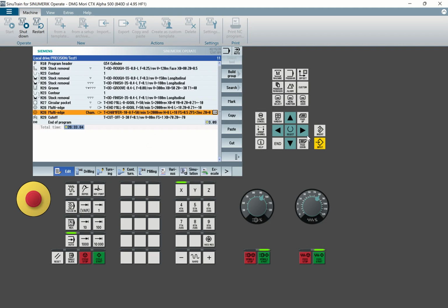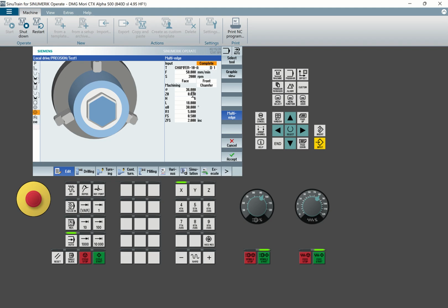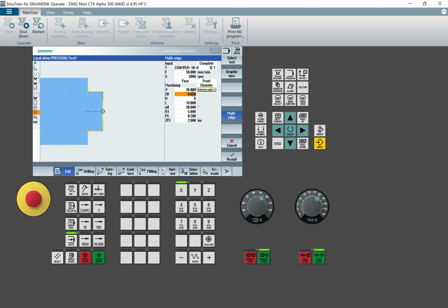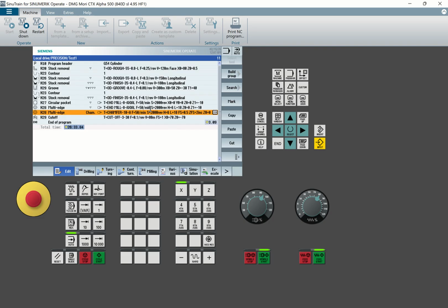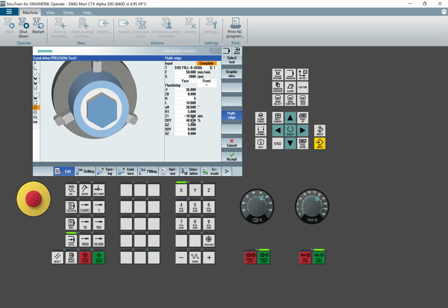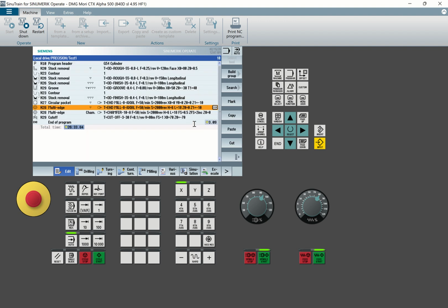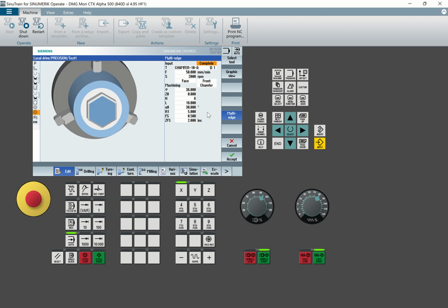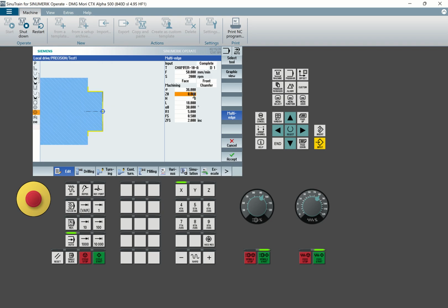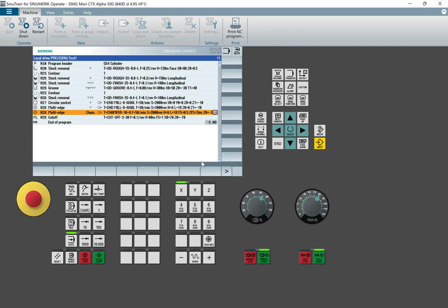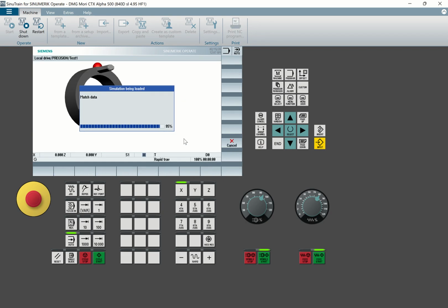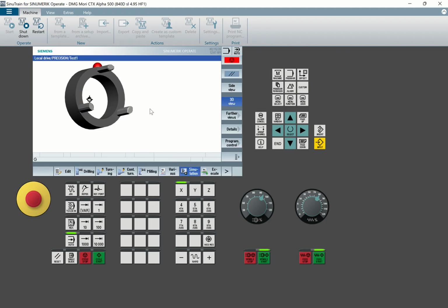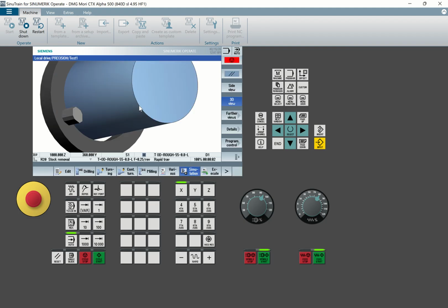So what you do, maybe you can offset our Z, because it's going minus. Let me check on this one to know the length I'm going inside. I'm going -10, so already it has cut 10, so I can offset here to Z -10. Okay, then let's do a simulation to see where the chamfer will cut. So this is how you can do a program.